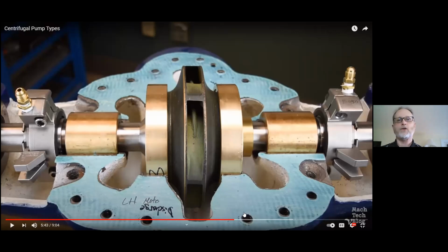Because the casing, now you do have to take the pump out of service. Whereas you can replace the wear rings or the shaft sleeves here on either end without having to take the pump out of service. So you can see the shaft, the wear rings, and then the seals. And these you can see mechanical seals on either end which prevent leakage back from where the fluid is being pumped into the exterior, whether the pump station or back towards the motor. The motor is over here.